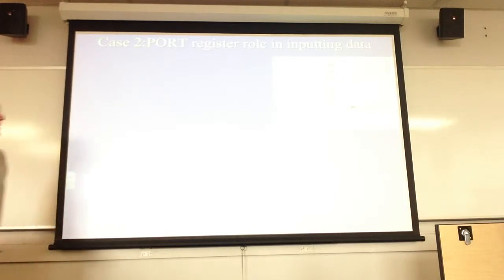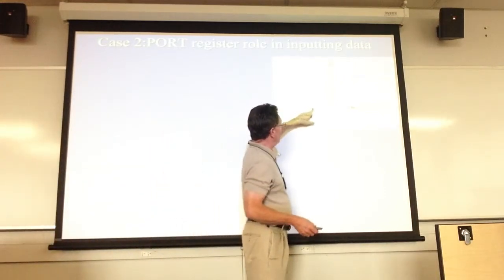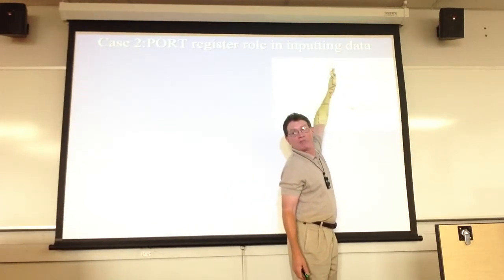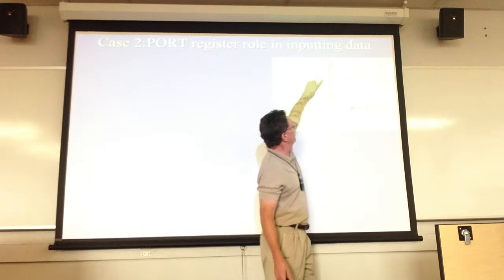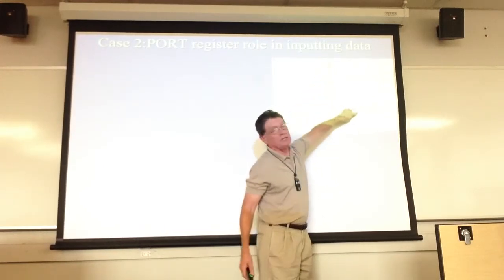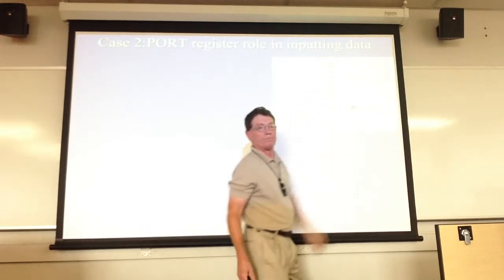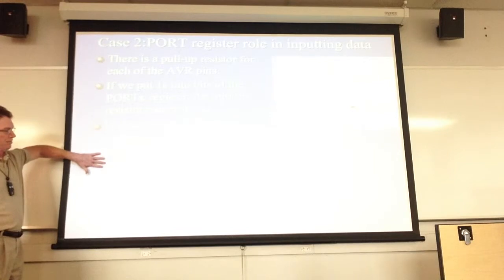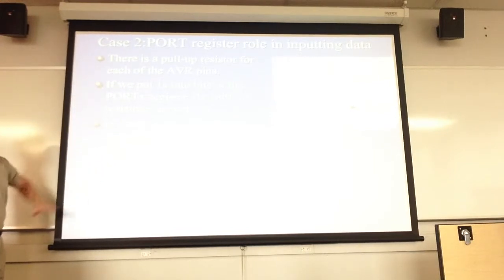All right. What effectively is happening here is, if I ground this pin here, I then have VCC, and that's going to activate that pin, all right? You'll see this. I'll run this for you, and it'll be a little bit clearer, all right? So in cases in which nothing is connected to the pin, or the connected devices have a high input impedance, the resistor pulls up that pin, okay? That's effectively what is happening there.